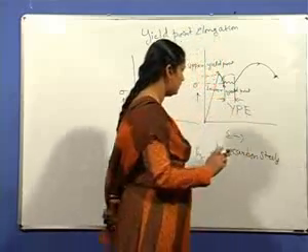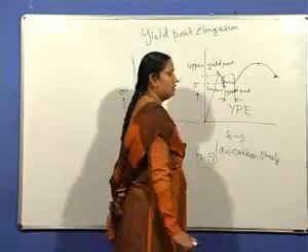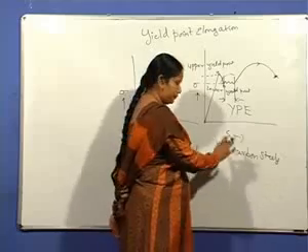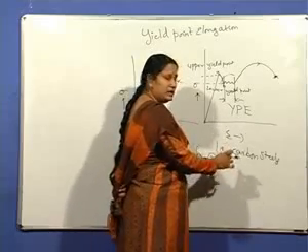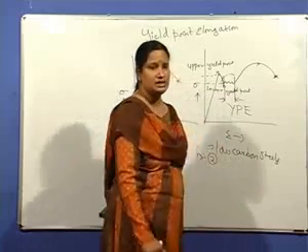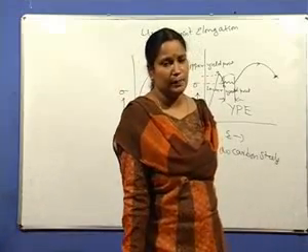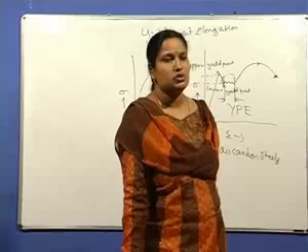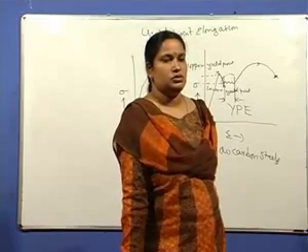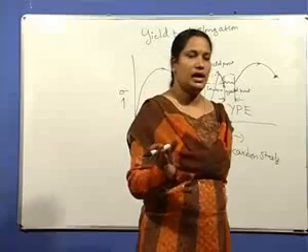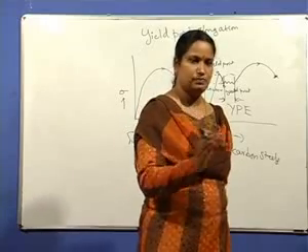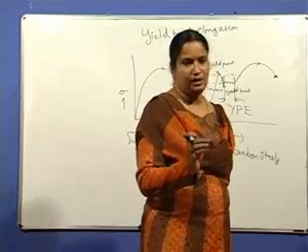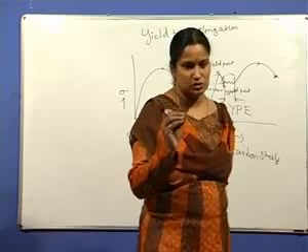But here, in order to explain why yield point elongation occurs in low carbon steel, and this occurs specifically in some materials, one main, well-known example is low carbon steel. So what are the reasons for this? I need to give you some introduction about solid solution hardening. Solid solution means solute atoms go into the sites of the solvent if they have somewhat similar size, or they go into the interstitial sites if they are much smaller.